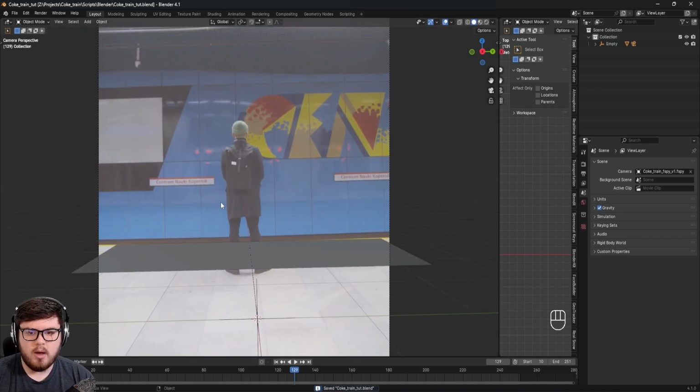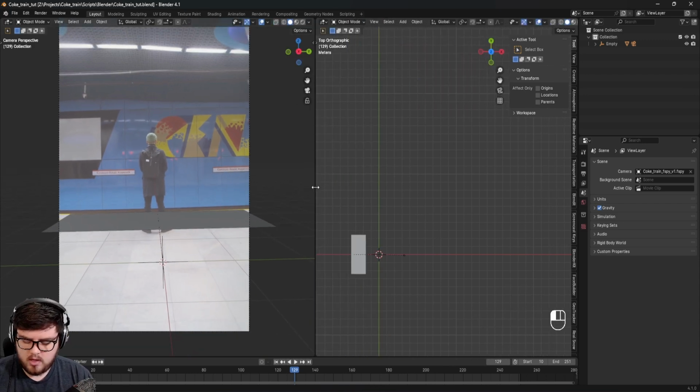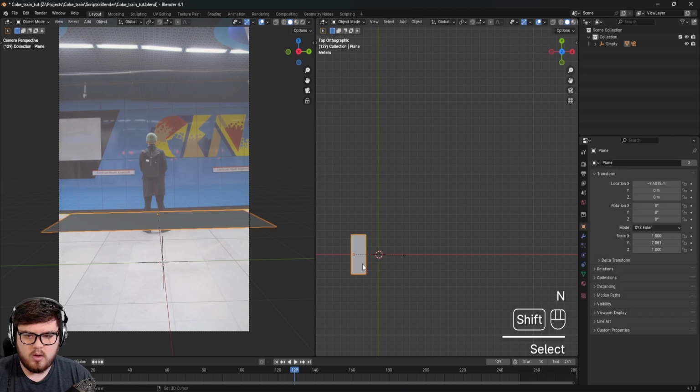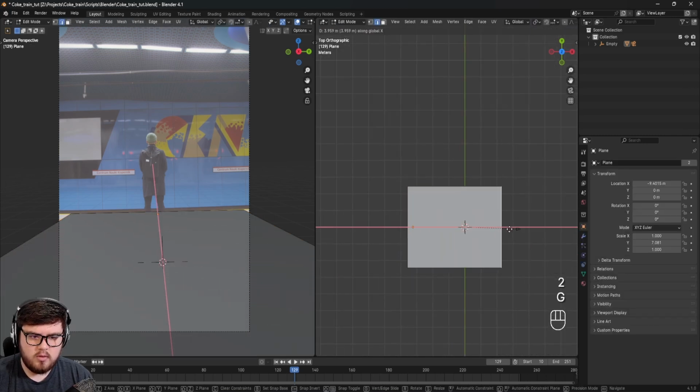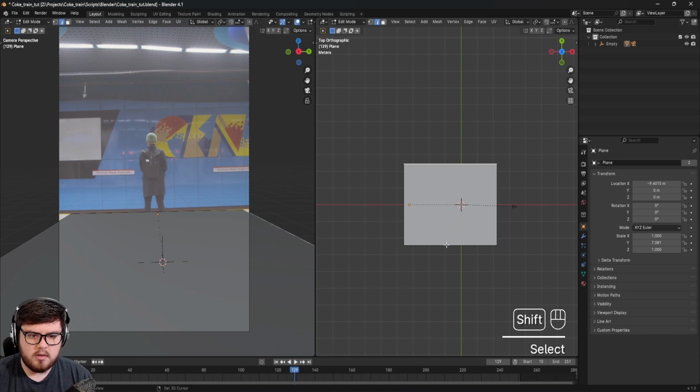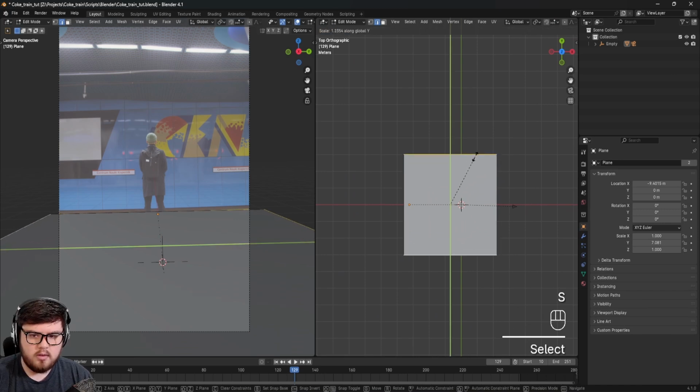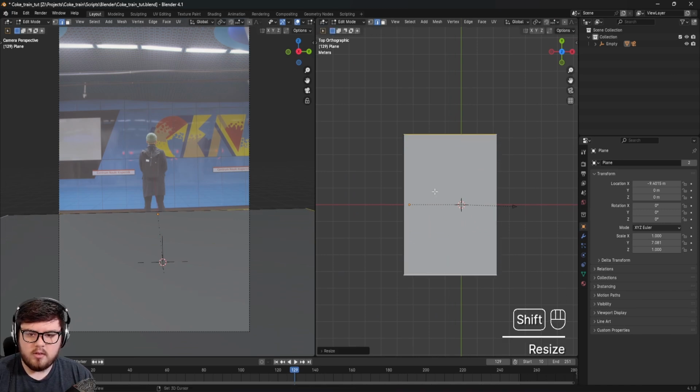So let's go ahead and model out this scene. This is to do with accurate reflections, accurate bounce lighting, all of that stuff. So let's quickly model this out. I'm going to come over here. We can go ahead and extend this out a little bit more. So we'll GX move that all the way to the camera. And then we'll also size this out a little bit, so SY to scale that on the Y. That is looking pretty good.